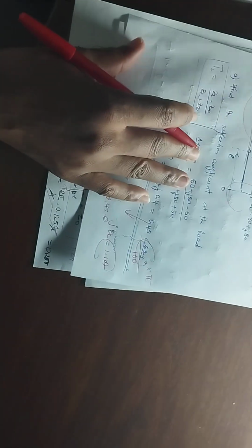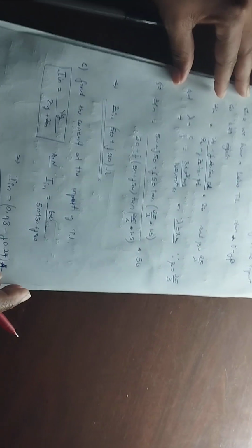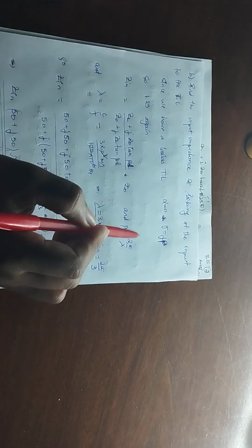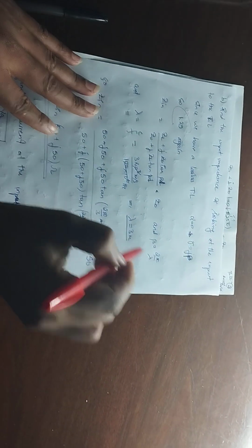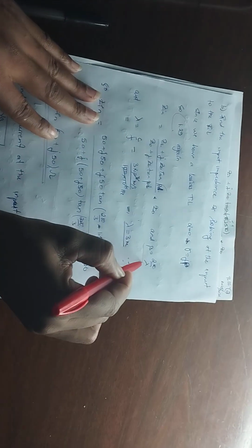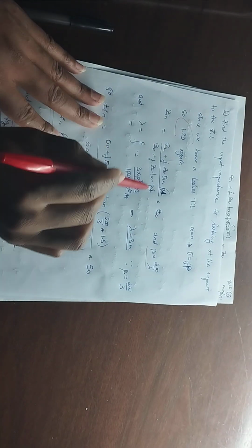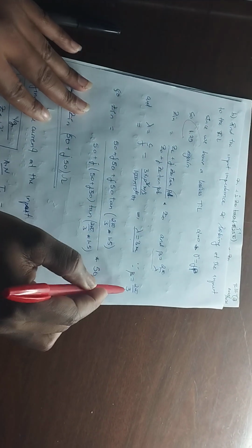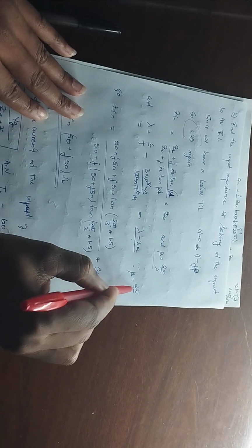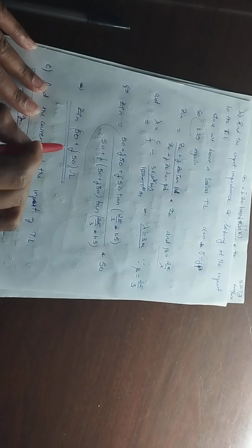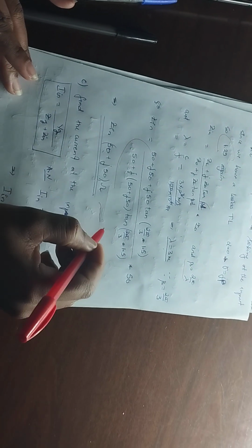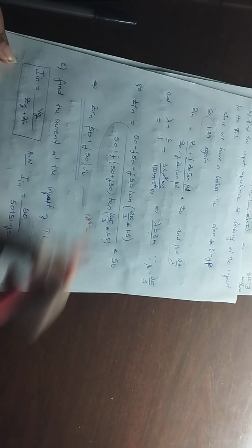To find the input impedance now, again the same, we need to look at the input. At the input, we need to apply the same equation 1.29. We have this. We need to find beta d. We have beta equal to 2 pi over lambda. First, we find lambda. Lambda is 3. Then beta will be 2 pi over 3. Then we just apply it straightforward here. And you can see Z in is 50 plus j50 ohms. Of course, if you want, you can write it in polar phasor form.